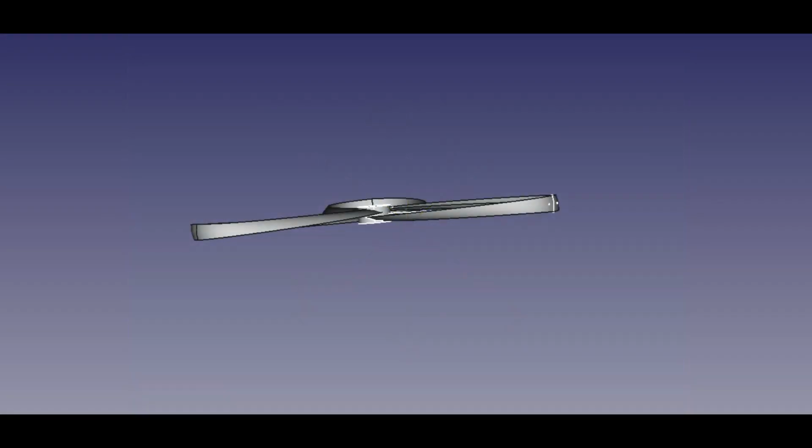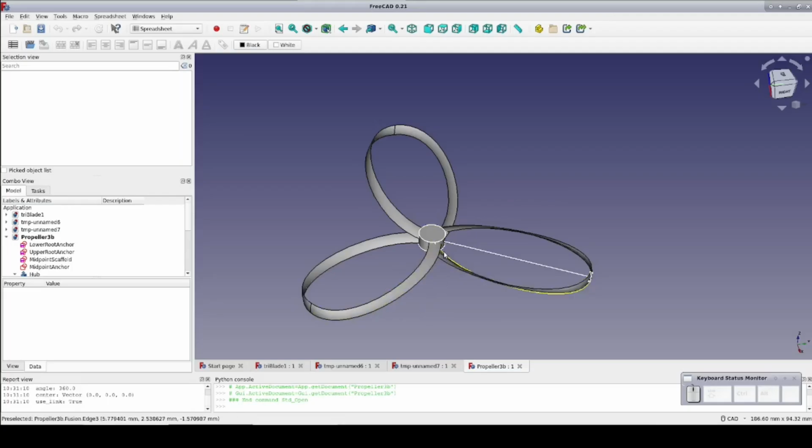In my previous video, I showed you a nice design for a toroidal propeller. It's not bad, but of course it's not perfect. One of the more glaring issues is the blade pitch. Because it sweeps from a root profile towards the midpoint rotated 90 degrees, the pitch of the blade increases outward from the hub. This is almost certainly exactly the opposite of what we want.